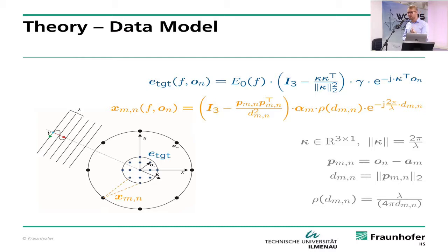You measure then with this field probe the relation between the antennas and the different points here, and then you can calculate the field. So in this equation, it's all a relative thing, and usually we do power calibration not afterwards, but in an iterative process. If we choose, for example, a GPS antenna and we emulate the signals, it's hard to define the power levels of signals that are below the noise level. So we measure with a GPS receiver the carrier to noise ratio, and we adapt it to realistic values that we have outside. That's the process.